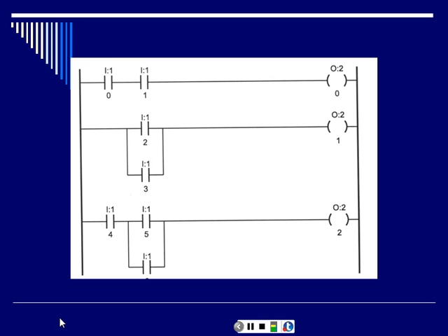That's right. But if rung 1 is working, it's not a power supply. So if anything on this was working, then I know it's not a power supply. So I'm assuming that something on this one's working. Okay, let's just say it is. Rung 1's working. But the problem is nobody addressed it. You didn't write something down to let somebody know what it is.